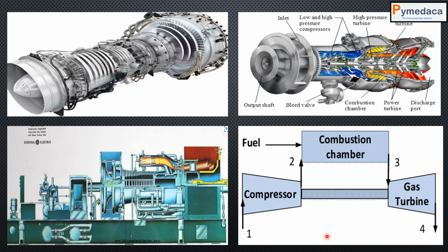Definitely I fully agree with you that there are some stringent requirements for the turbine piping as well as compressor piping with respect to the pipe support, stress analysis and loads and everything that needs to be complied with, but you will be coordinating with the respective stress engineer in order to get it done. So your intention is to see the nozzles of the compressors and turbines, the nozzle orientations, and how to plan the routing accordingly, so you don't have to be fearful about any major equipments.